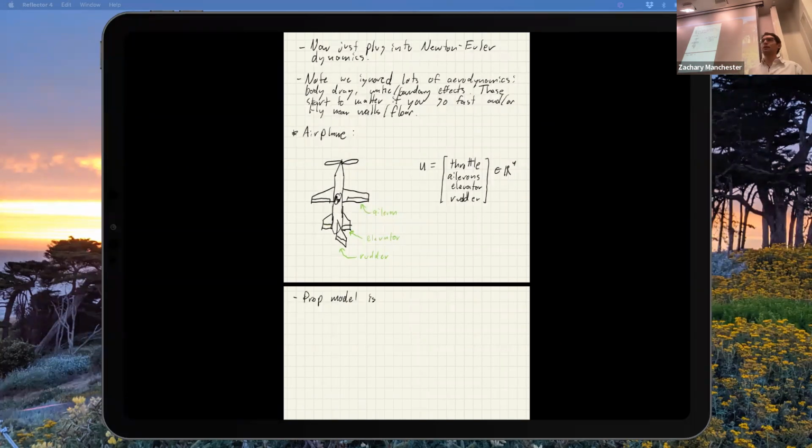It turns out when they build small single engine airplanes, they actually trim the airframe at the factory so that at cruise, it's at equilibrium. They cancel out the prop torque at cruise. That's baked into the airframe, which is kind of wild. So the airframe's slightly biased and twisted, so that all the lifting surfaces have that baked in to cancel out the prop torque at cruise.